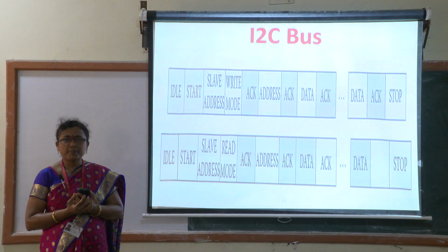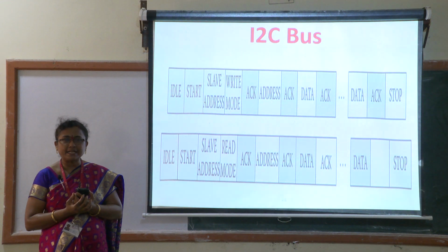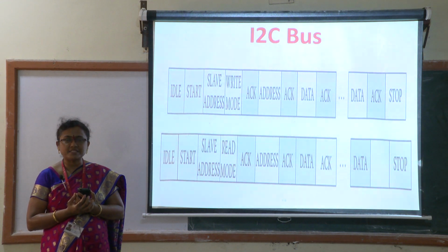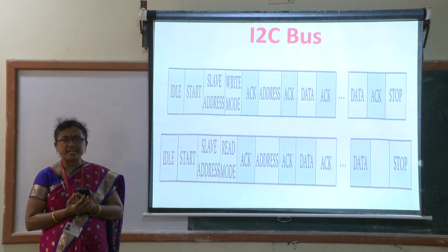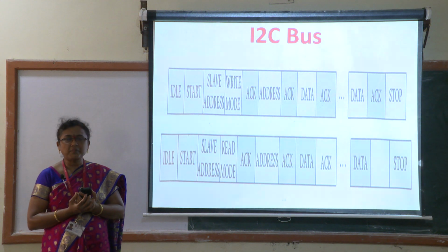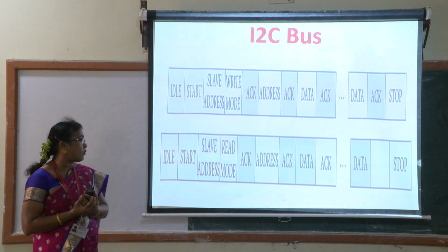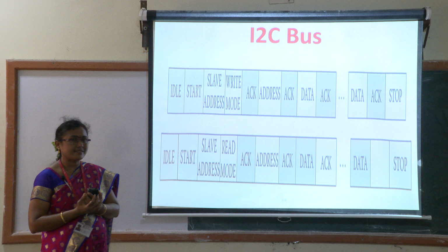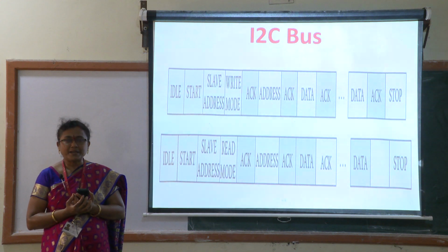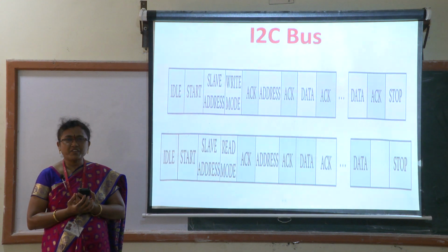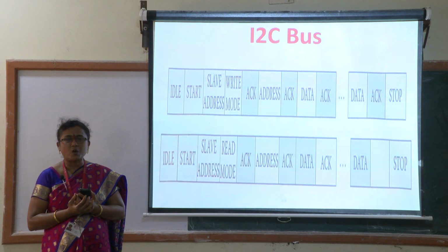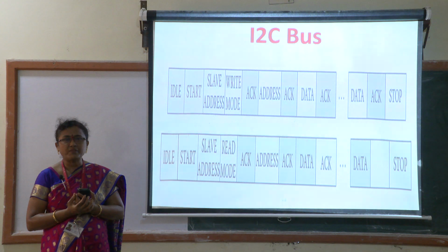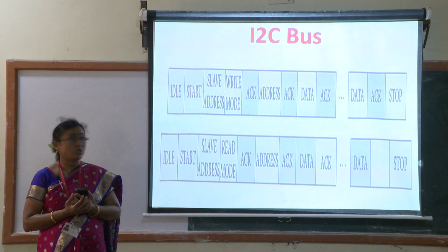So that time, depending on the transmitting, it is a read, and again when the acknowledgement is received, it is the write of data. So the reading and writing you have to mention. Reading means 0, writing means 1. And the next one is the address. The address will be particular to the node, because I have many nodes, and for each node you have to categorize how many addresses are required. In addition to the slave address, this address is also required.